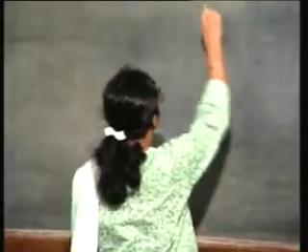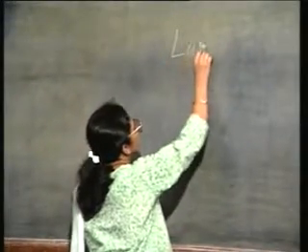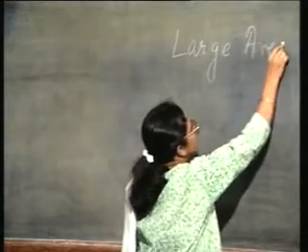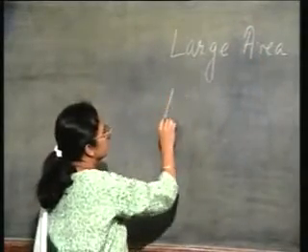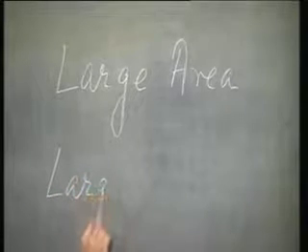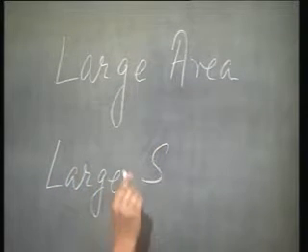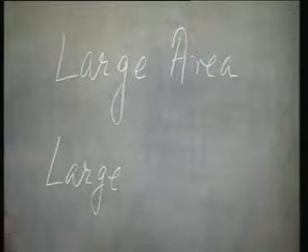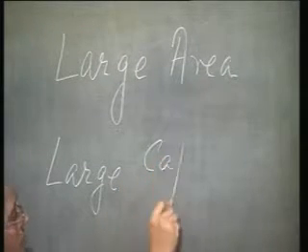So, you see basically the PN junction isolation technique has two major drawbacks. The first drawback is the large area requirement, and secondly it has the adverse effect on the speed by having a large capacitance.